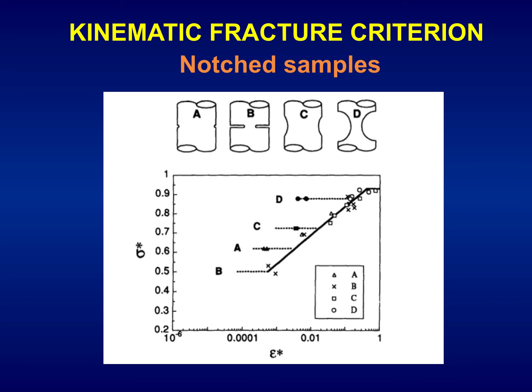With regard to the left-hand side asymptotic values for the quasi-static test, quasi-stationary test, steady-state condition for hydrogen diffusion, equilibrium condition for hydrogen in the metal lattice is achieved for a very slow test, and in this case the asymptotic horizontal value depends on the geometry and on the triaxiality. But the order is really beautiful. It's BACD. It resembles BACH, Johann Sebastian Bach, the genius, the best musical composer ever.